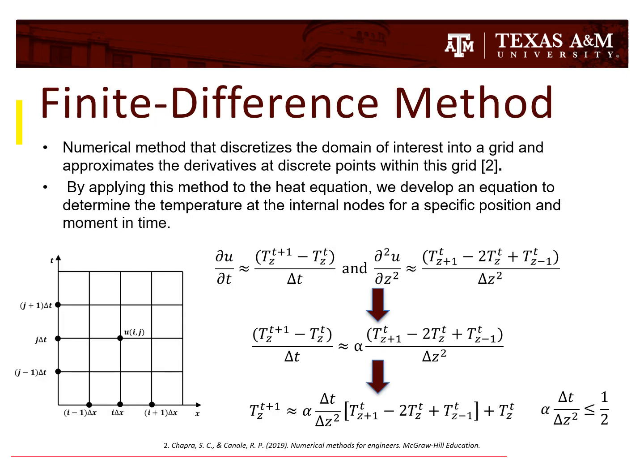This is the application of the finite difference method on the heat equation. The finite difference method is a numerical technique which approximates solutions to differential equations by discretizing them. We will apply this by dividing the spatial domain into discrete points and approximating the derivative with time differences. The resulting equations will be iteratively solved using MATLAB.